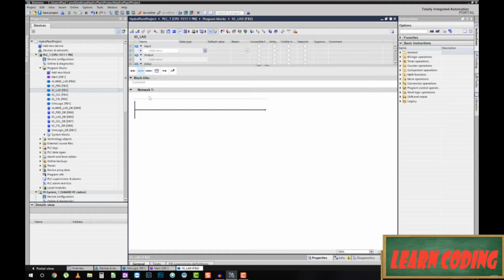To start with, I think I'll go with digital output because I really don't need to do anything with digital inputs in here. Those are going to be evaluated elsewhere throughout the program logic. So in here, I don't really need to alias these, or set them equal to other registers or anything like that, because it's real easy to change I/O in this environment anyway. So let's go ahead and start with digital outputs, and I'll need a way to control those.